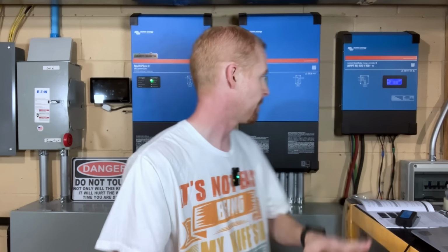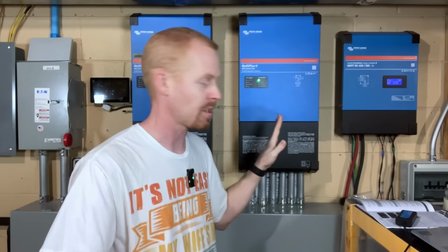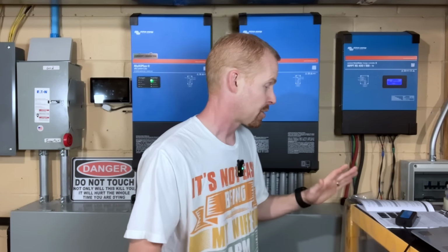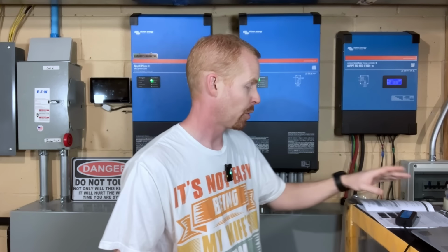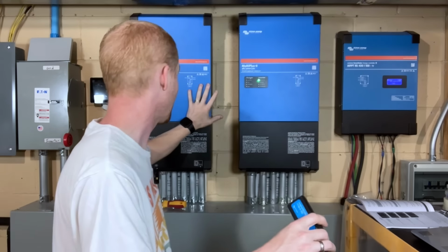So first off, we're going to need to connect to the inverters using the software. There's actually, again, with the customizations in Victron, there's a lot of different ways to do things, so much so that it can actually overwhelm some people. I love the different options for customization. So what I'm going to do this time is I'm going to use the Mark III to USB interface to connect directly to my inverters to view the programming. There are ways that you can download all of your configuration from the VRM, and I'll get into that in a completely separate video as well.